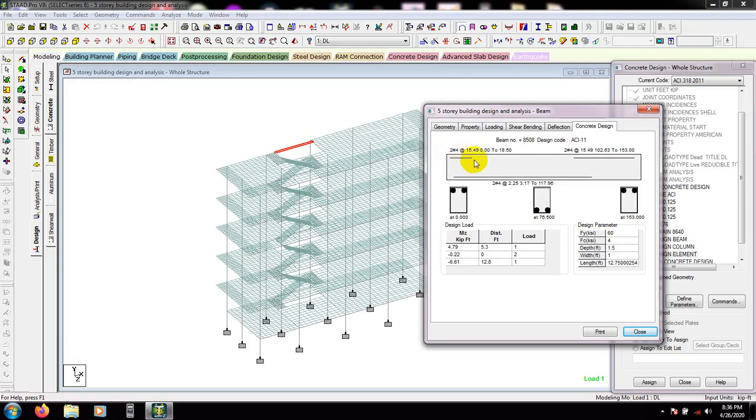From that distance to that distance, the distance is also given, 0 to 18.5 inch, and for the bottom, from that distance to that distance, 4 number 2 bars required from distance 3.17 inch to 117.96 inch, like that. We can find our detailing.